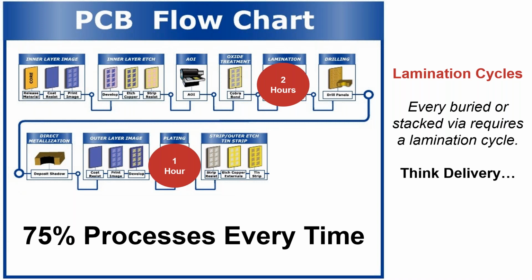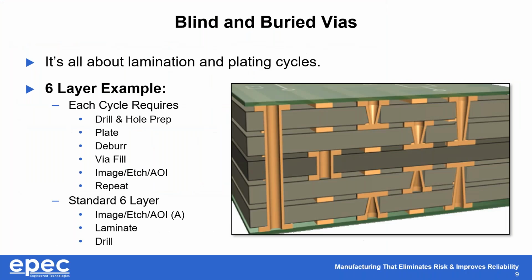And we're going to get into more of how each of the individual features kind of stack up here. Because when you look at this traditional 6-layer printed circuit board, this particular board has not only microvias in it, it's got buried microvias, traditional microvias, blind vias, and a through-hole via. And what this particular board means, from a 6-layer perspective, is you're talking about 3 lamination cycles, right?